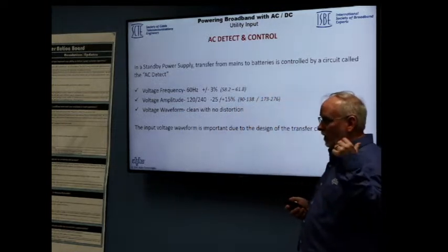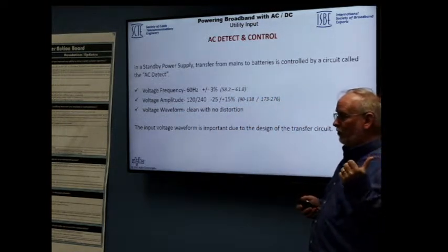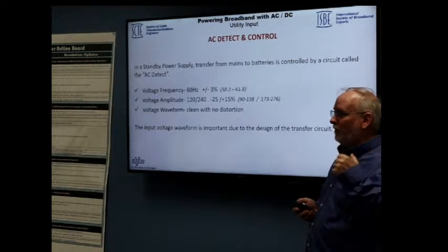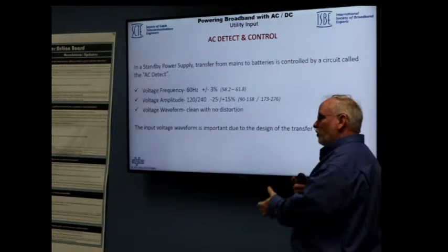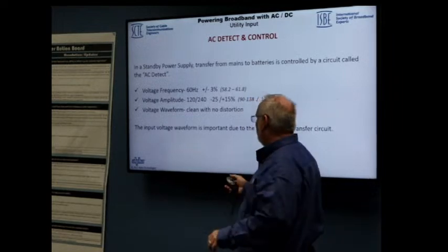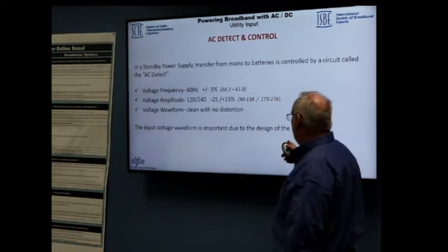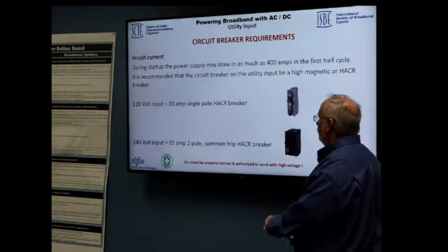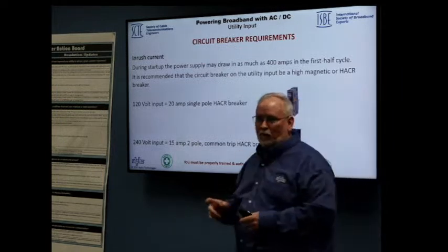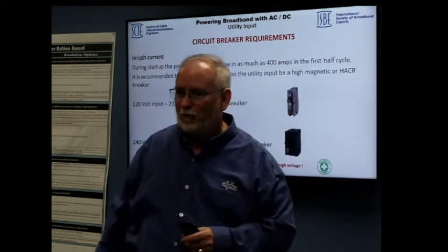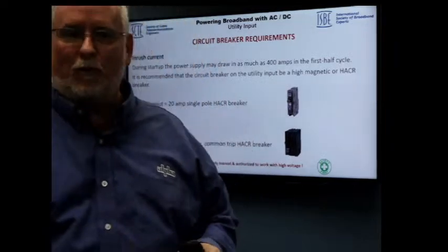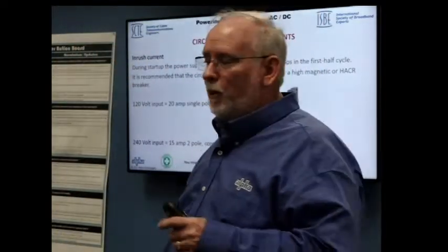If you stick a generator on the front of a power supply, if that generator is dirty, that will never connect to it. So you have to have a good regulator, good brushes, everything has to be good in that generator. The input waveform is important due to the design of the transfer circuit. Circuit breakers, I saw one laying over here somewhere. Maybe it's on the other table. But circuit breakers are important.